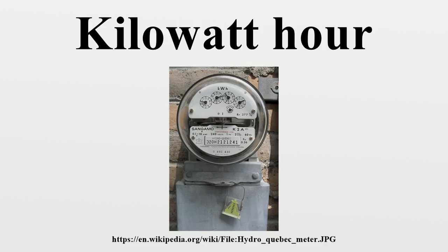Cost of running equipment is the product of power in kilowatts multiplied by running time in hours and price per kilowatt-hour. The unit price of electricity may depend upon the rate of consumption and the time of day. Industrial users may also have extra charges according to their peak usage and the power factor.